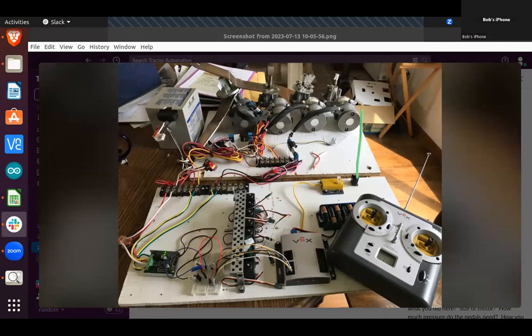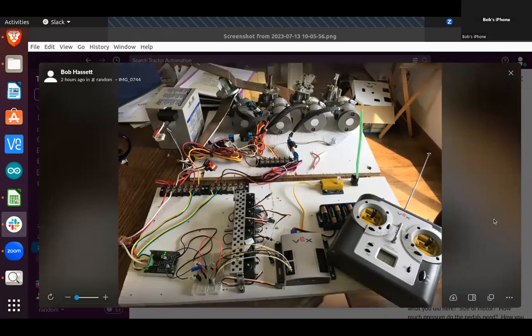That VEX, that silver box, does put out pulse width modulation, and it has places for 8 motors, which can be the toy motor or the servo motor. And I'm using 2 ports to jump over to the breadboard, and then I've got a motor controller just left of that.